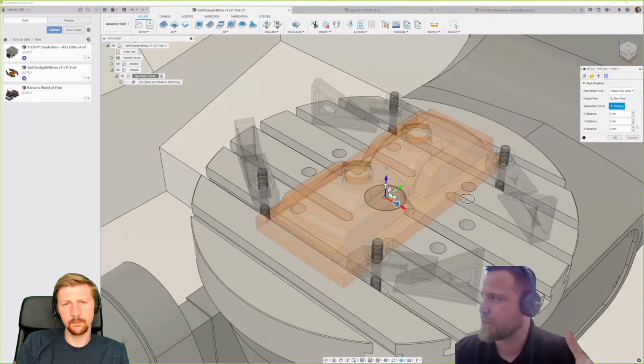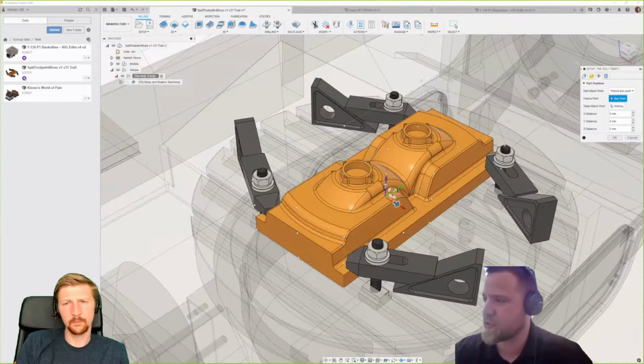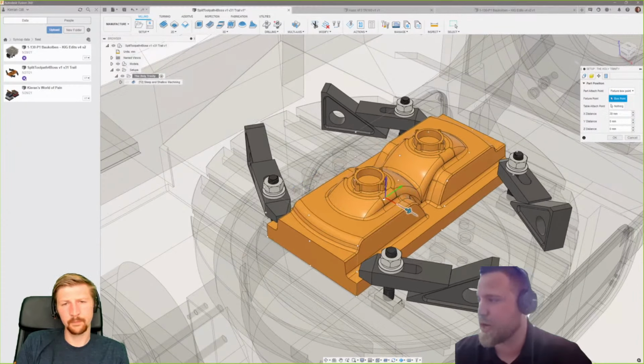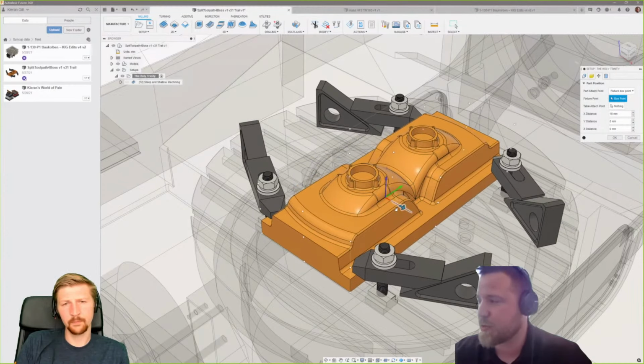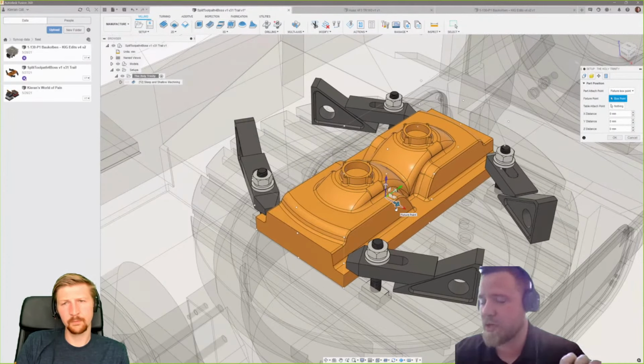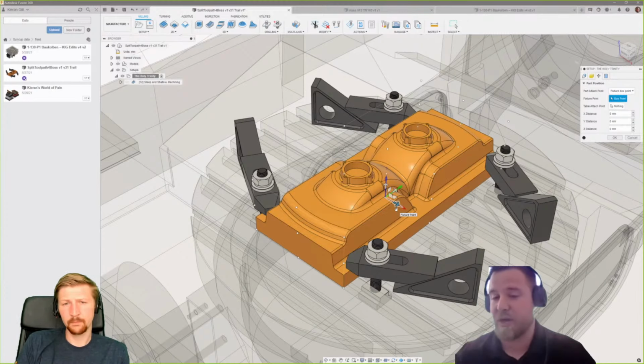And you also have, if we go back to this fixture point for just a second, we've given you a number of different drag handles as well to go and pull and drag the part around. Now, what you will see is that we haven't included a rotational component. And that is purely because we are strictly aligning the axes of the part to the axes of the machine. So therefore, we haven't provided a rotational component. And really the reason behind this is because currently we're not supporting the ability for users to start with their A or their B axis at -90 or positive 90 degrees. So hence why we don't have that rotational component.